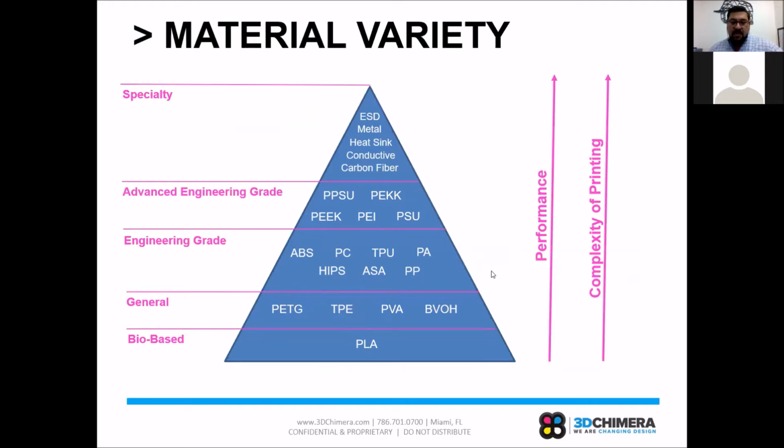These types of materials are commonly used in the industry and tend to be difficult to print on some of the low-end 3D printers, mainly because these materials often have a high shrink rate, and it's super important to have a very controlled print environment to make sure that there's enough heat surrounding the part so that shrink rate is predictable and controlled, and that you're not fighting the artifacts that come from a part that's shrinking, which are maybe like curling or cracking in your parts.